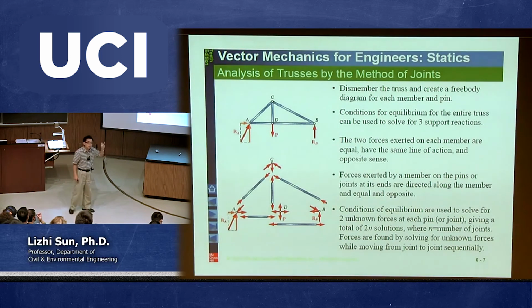After you calculate those forces, if the calculation gives you a positive number, then in reality the result is consistent with what you assumed. But it can come out with a negative sign. If that's the case, in fact, your assumption was wrong. But your assumption is perfectly fine. In other words, you don't have to recalculate. You just simply change the direction.